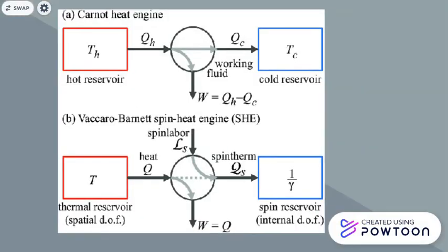The Carnot engine was created to examine the efficiency of a heat engine. It is idealized as it has no friction. Each leg of its cycle is reversible. The Carnot cycle consists of 2 isothermal expansions, where delta T is equal to 0, and 2 adiabatic expansions, where Q is equal to 0.